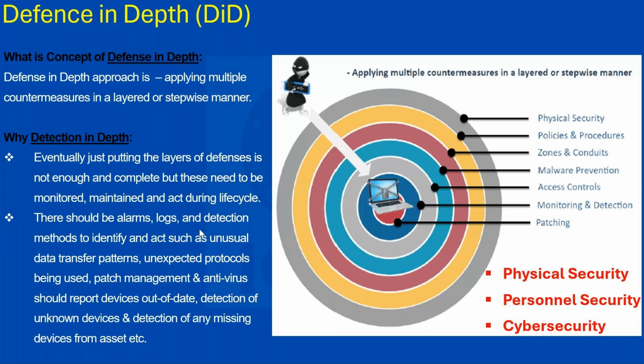Then there are other ways around malware protection. There is antivirus, there is whitelisting, there are other tools which get deployed. Again, when we say whitelisting or antivirus, it is not exactly like what is typically done in IT, but it is usually tested by the legacy vendors. They check whether it is fully compatible, and only then is it deployed. The purpose is that latency issues shouldn't come.